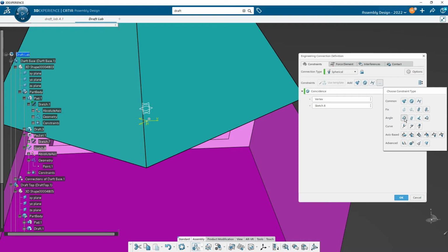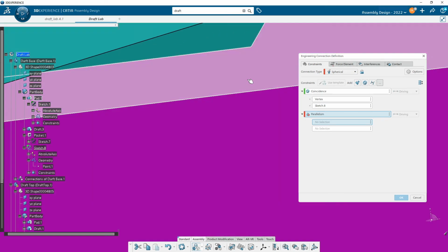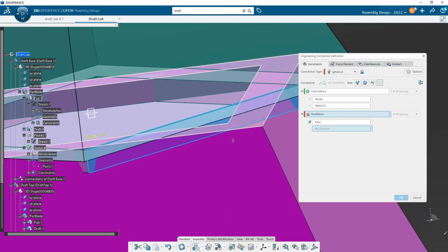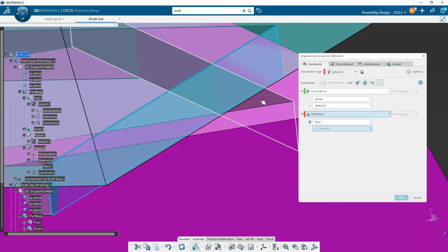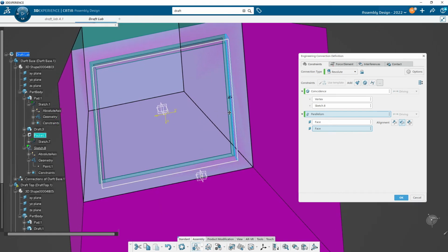One thing that was pretty common, if you thought that you ever wanted to turn it, but right now you wanted it to be parallel, you would make it an angle of 0. And then later, whenever you want to edit it, you could just click on that constraint and change the value. So I'll come over here and I'll hit parallelism and then sneak in here. You have to get kind of used to this. Get in there. And then you pick this right here. And look at that. So now it's parallel.